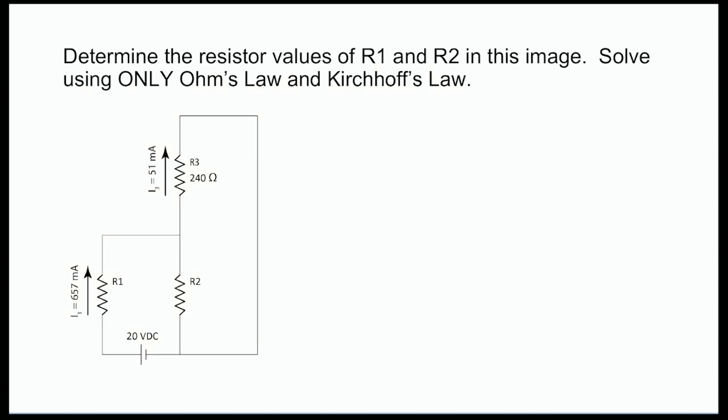Sometimes with examples like this, you are going to be asked to use only Ohm's law and Kirchhoff's law, as opposed to, as you can see here, being able to use a divider law, whether it is a voltage divider or a current divider. First thing you're looking for is, can I use Ohm's law anywhere? Can I use the law of V, which is voltage equals I multiplied by R, which means I need to know at least two of those three to calculate the third.